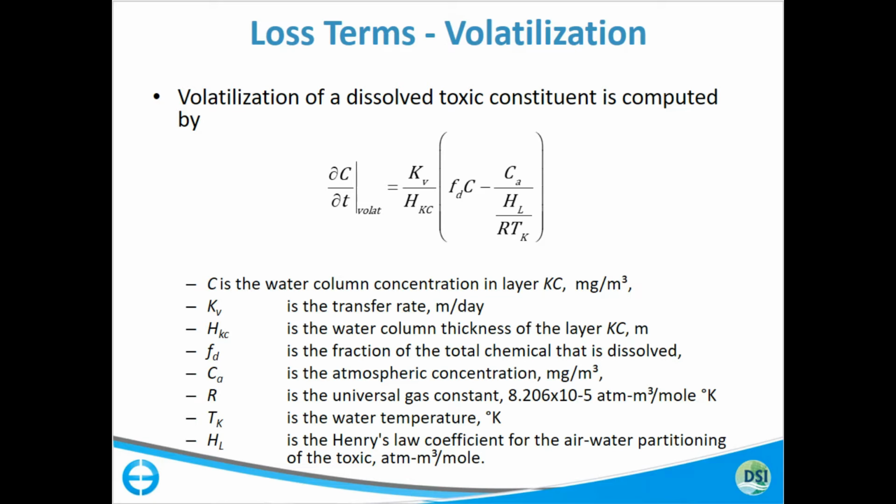Then you've got your atmospheric concentration, Henry's law, and the fractions. Is it dissolved? Because you can only volatilize the dissolved fraction. You can't volatilize the sorbed fraction. So, anyways, that's the basic equation.